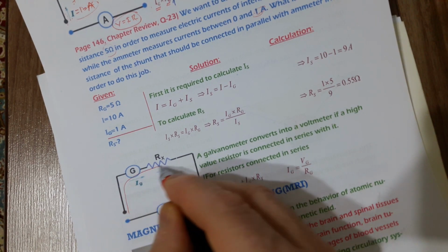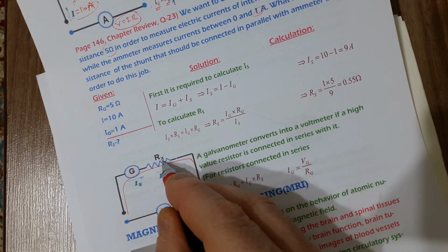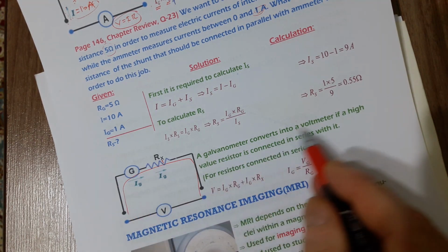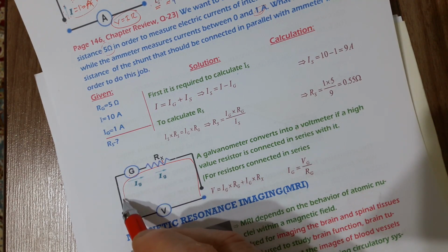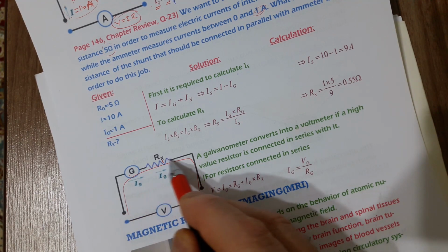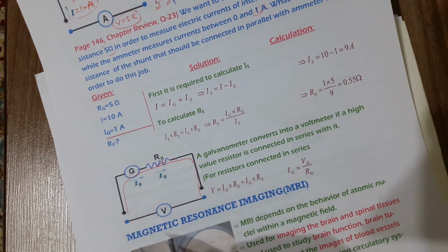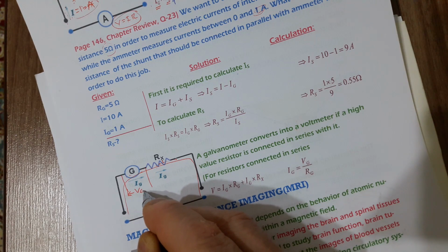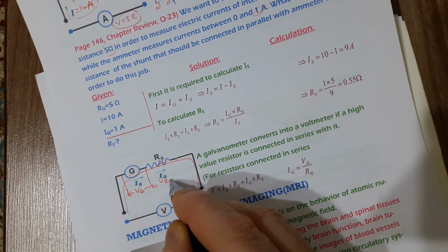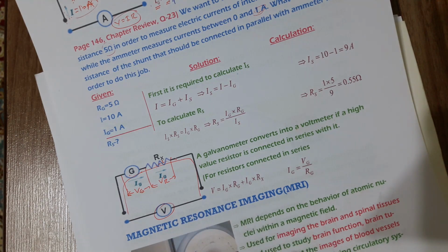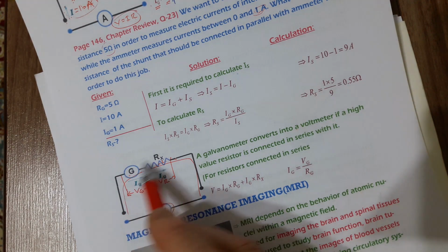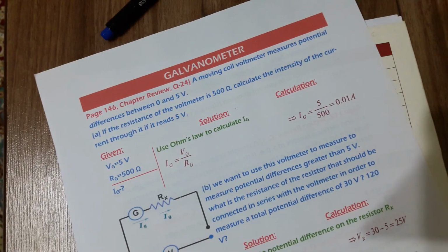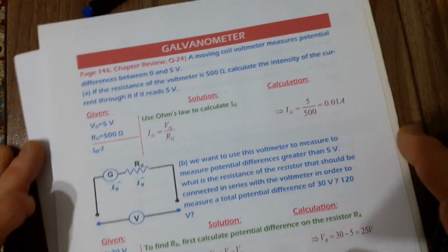So then, electric current passing through the circuit will be smaller if the resistance is big. In series combination, because the high value resistor is connected in series with the galvanometer, the electric current will drop, but the same electric current will pass through the galvanometer and the resistor. But right here, the potential differences are different. The potential difference on the galvanometer plus the potential difference on the resistor, the addition of them, will be equal to the total potential difference of the circuit. So then, by using these two equations, I'm going to answer the question related to the galvanometer used as a voltmeter.